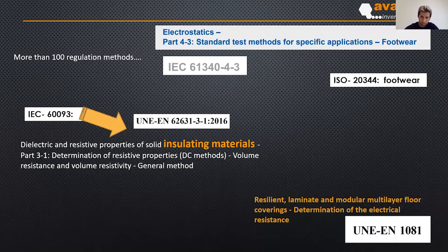The first point that is very important is that we need to stabilize the sample. It means that we cannot make the measurement in just any condition. We need to put the sample in some determined condition for some time. For example, the typical is 4 days at 23 degrees and 50% humidity. After that, we take the sample and make the measurement. It is very important, and later we are going to show why.